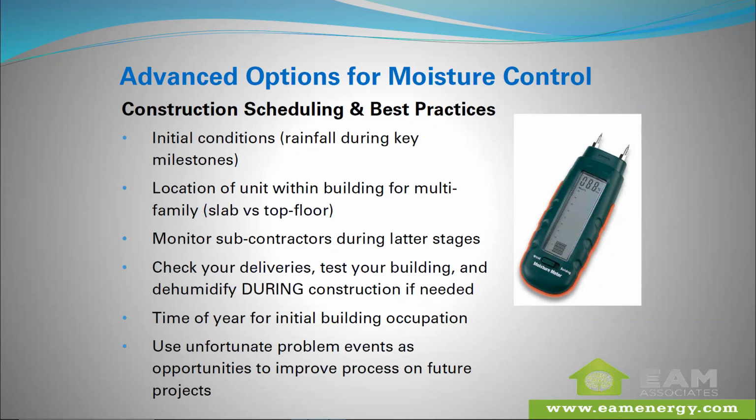We found subcontractor behavior needs to be monitored. If you're a builder, if you can't require things of your tenants or homeowners, that's understandable. But I think certainly you can require your subcontractors. It's very common on projects to find windows and doors open on the later stages of projects, especially during spackle and painting, and then the AC cranked down to 65 degrees on the thermostat. So you're damaging buildings before people are even moving in.